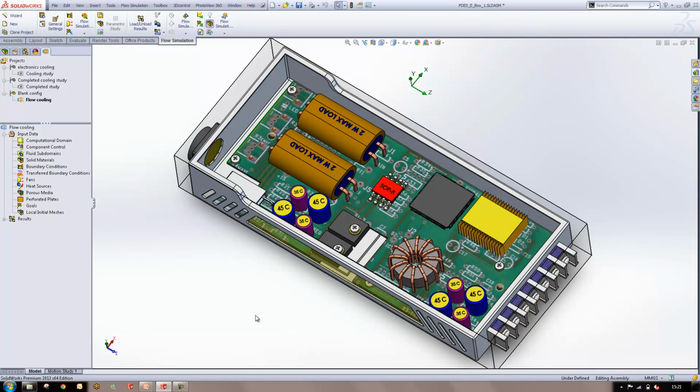Okay, so what we're looking to do here is make sure that our heatsink, so that's this guy over here, is coming in at below 59 degrees C, and our op amp, that's this guy here, is coming in at somewhere below 51.6 degrees C. So these are our expectations, so that's what's going to dictate whether our design is successful or not. So first thing we need to do is go ahead and start specifying the materials for our components in here.